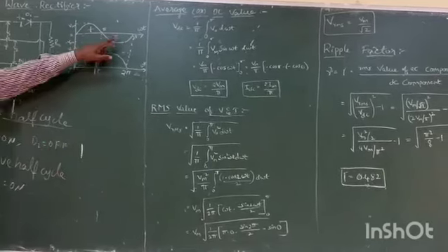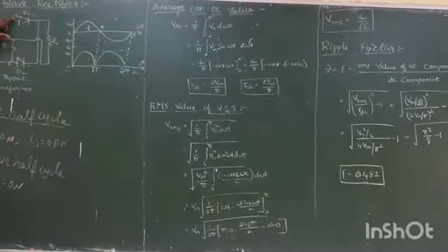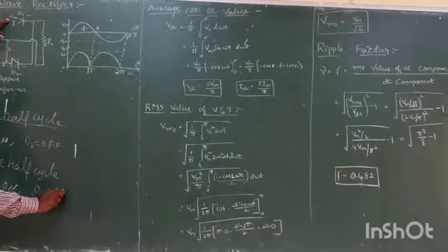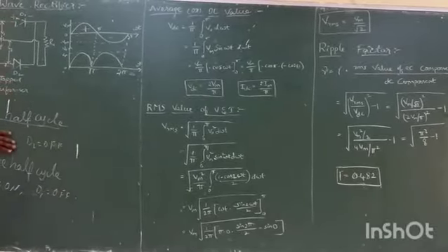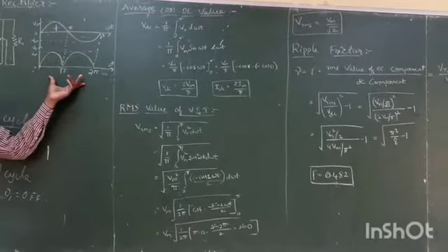During the negative half cycle, D2 is on and D1 will be off. This is how the full wave rectifier generates the output signal in the form of DC.